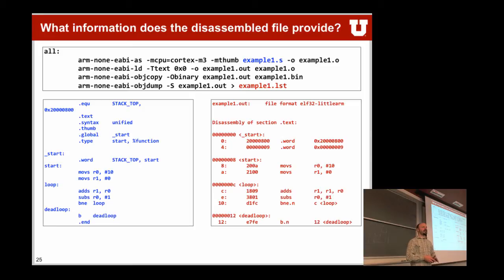It's actually telling the microcontroller that whatever is at this location is a thumb instruction, not an ARM instruction. So if this were 8 in here, it would mean that wherever you jump to is an ARM instruction. And if you ever try this on your Cortex-M3, you will get a hard fault, because the Cortex-M3 cannot execute ARM instructions.